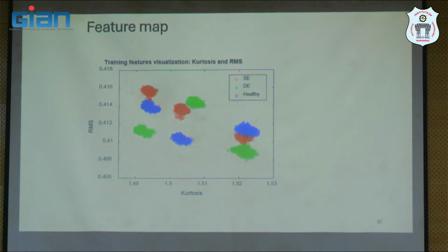This is, for example, one level, for a voltage level only, that we are using. In that itself, we have fixed the features. Voltage is the raw data. From that, we extracted features, kurtosis and RMS. And because I know the ground truth, I know whether this is healthy condition or faulty condition, static or dynamic, so I could color code it.